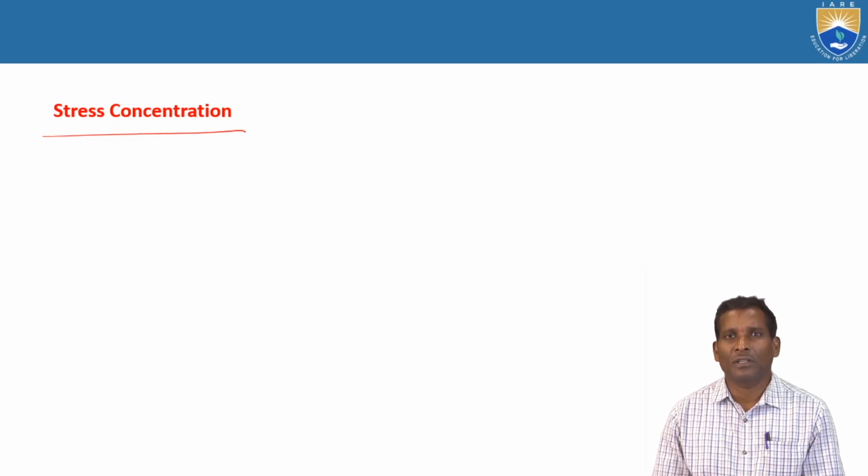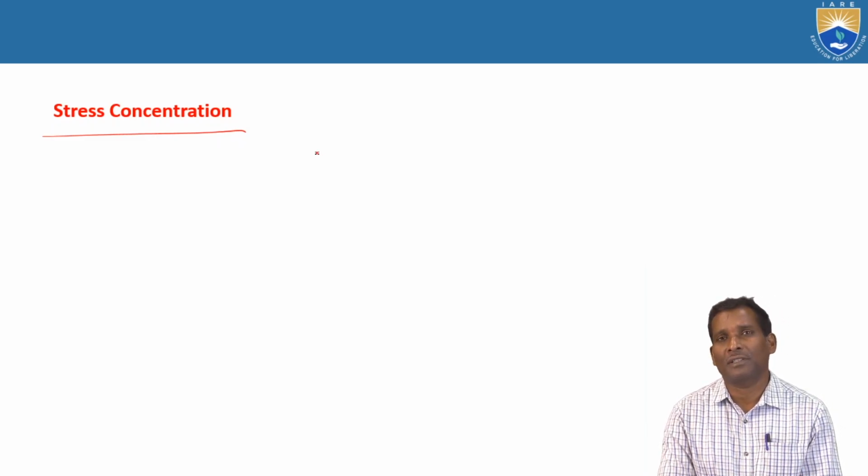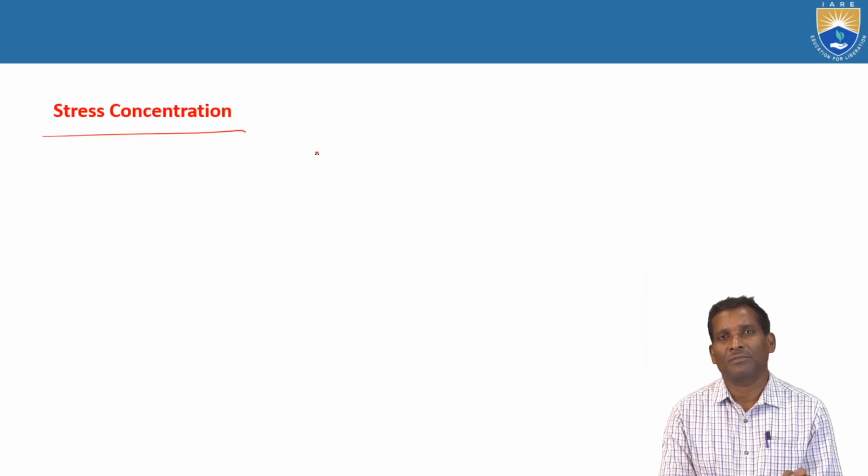In that case, there is no stress concentration. Wherever holes, notches or pockets are available, meaning whenever the object changes its cross section suddenly, more stress will occur there. This phenomenon is called stress concentration.